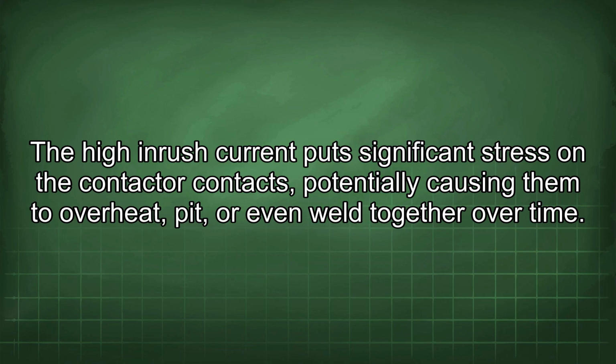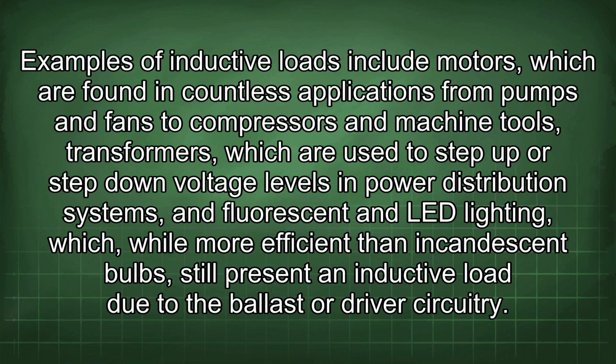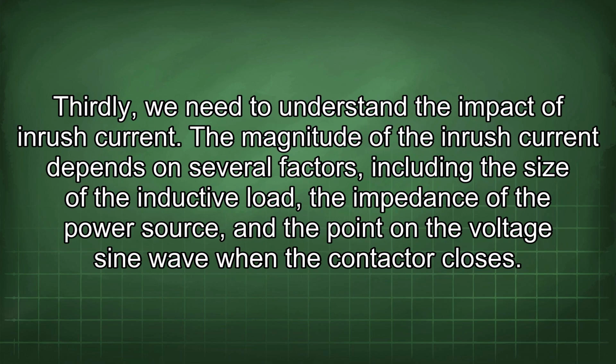Examples of inductive loads include motors, which are found in countless applications from pumps and fans to compressors and machine tools, transformers, which are used to step up or step down voltage levels in power distribution systems, and fluorescent and LED lighting, which, while more efficient than incandescent bulbs, still present an inductive load due to the ballast or driver circuitry. Thirdly, we need to understand the impact of inrush current.